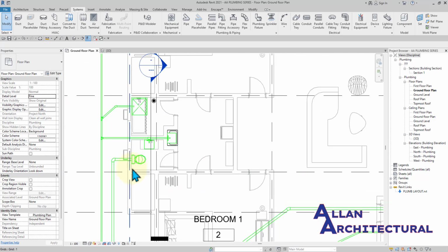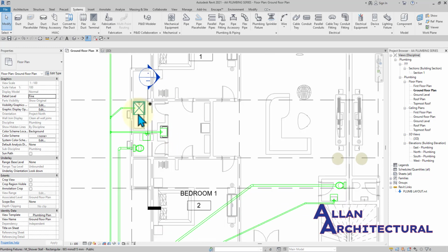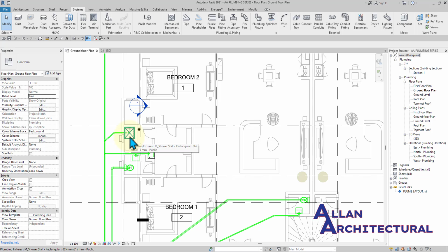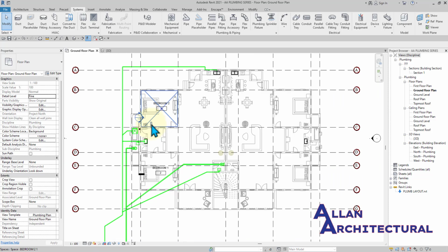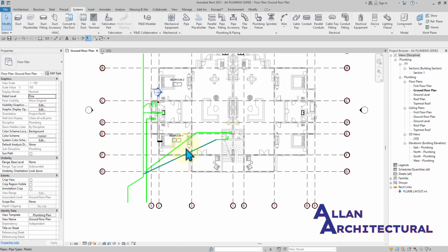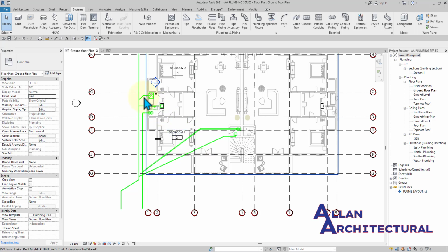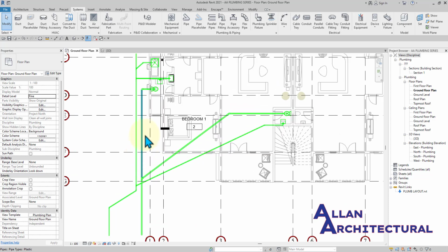Even though we have the trap systems inside of the WC, and we have some trap systems also inside of the wash basins, the sink, and then the bathtubs as well, it's very, very important that you separate those lines. I've seen several plumbing drawings that just use the same line, where everything is connected to the same line and discharged out of the building, which I do not find advisable. So just make sure you separate those lines.